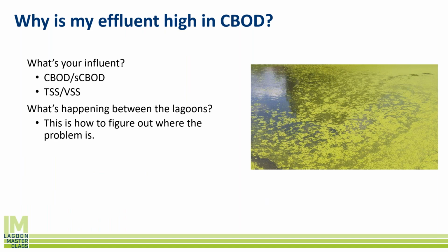And whenever we went back and we actually started taking samples, because the headworks had changed, the equalization tanks had changed, everything had changed, turns out the CBOD coming in the facility was actually over 1,000 milligrams per liter, and the ammonia was 40, but we're going to talk about something called total Kjeldahl nitrogen, which includes the urea and organic nitrogen. That was over 140.